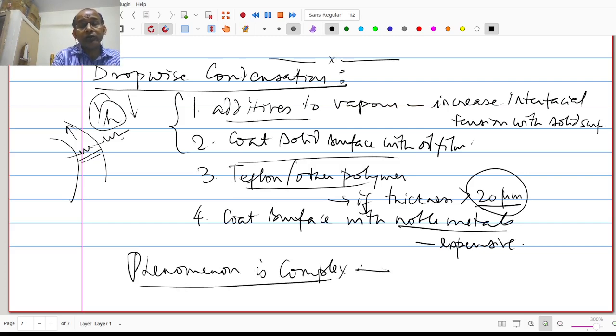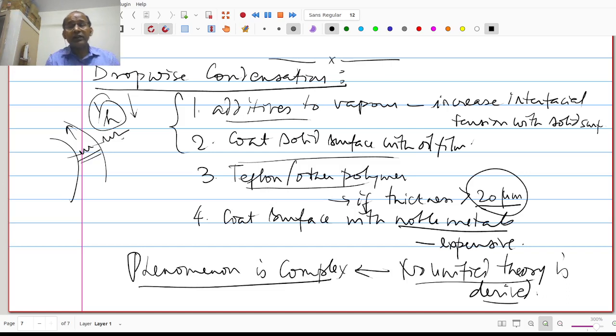So no unified theory exists. So you basically depend on practice or practical things. So what you normally do is to do a film condensation analysis, as was done in the earlier part of this lecture and the last lecture.